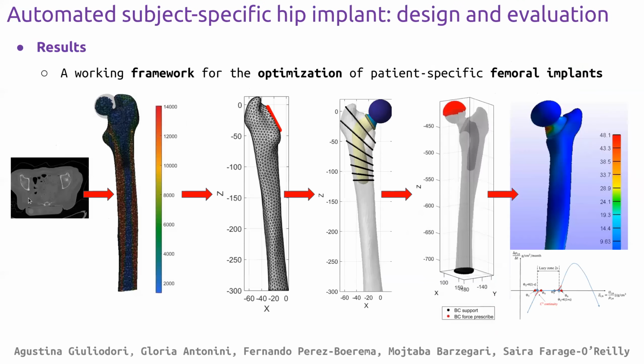Thanks. The implant is then produced based on the geometry of the patient and inserted into the femur. Meshing is done, and at this stage in the pipeline, the user can specify the type. The material properties are taken from the grayscale of the CT scan and applied to the model. The boundary conditions can then be applied, and the model is ready to be run. The specific parts we added here were deriving the geometry from the CT data and including subject-specific mechanical properties.